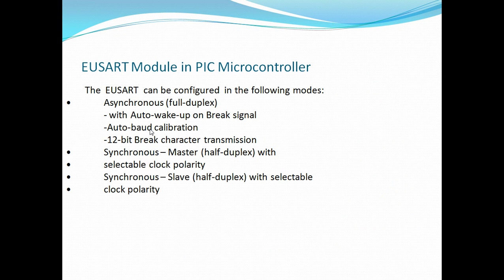data communication equipments. Okay. PIC microcontroller supports both types of communication. It supports asynchronous mode of communication as well as synchronous mode of communication. So this EUSART, that is Enhanced Universal Synchronous Asynchronous Receiver Transmitter module, can be configured in both communication modes, asynchronous mode, synchronous mode.